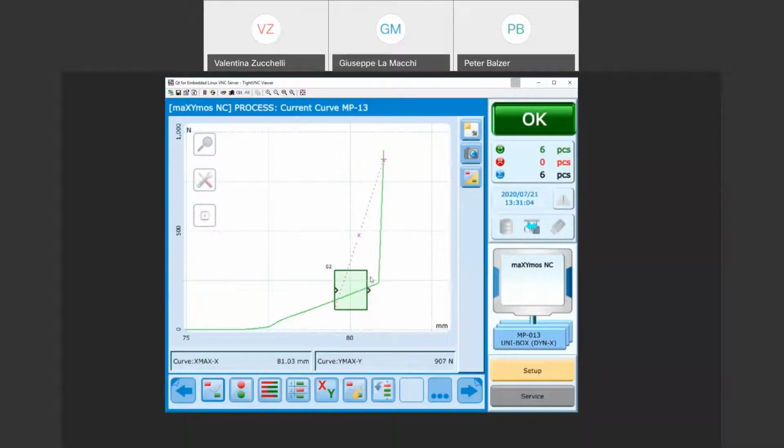If I would move this exit side of the window a little bit nearer to the block position, I would grab exactly the holding force of my bearing in this case, which is used quite often, for example, in the gearbox assembly. So again, just with one piece of paper, again, to simulate some tolerances of the machine. And now you see, you will always grab the holding force. So that's a quite useful function.